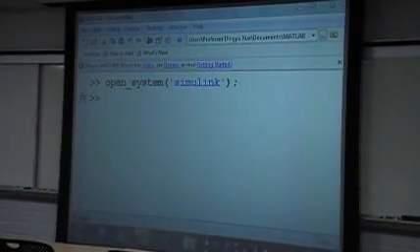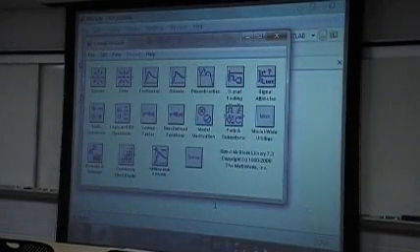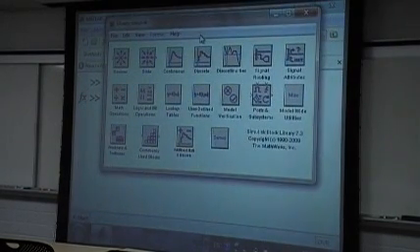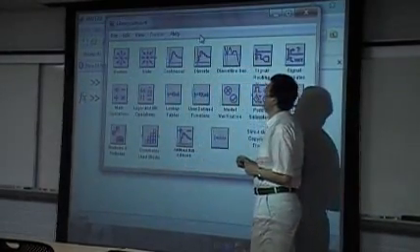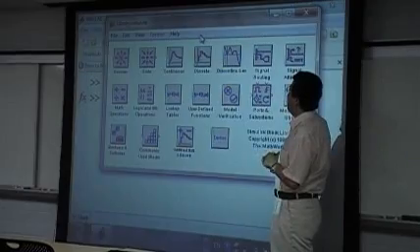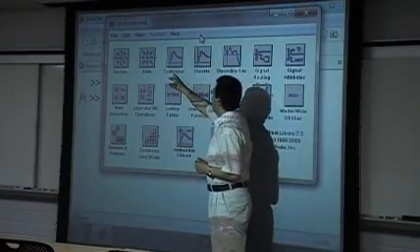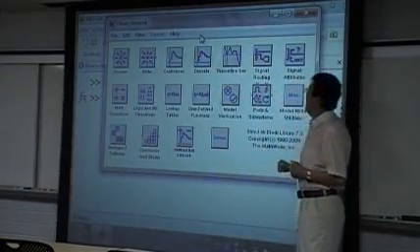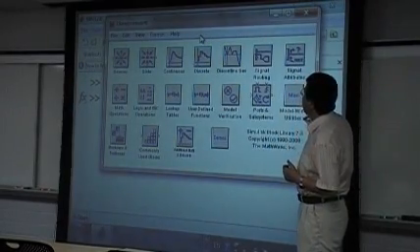If you start Simulink, you will have a library window like this, where you can see that there is a sources group, which is used for input signals. And then this one is used for output signals. You can display messages, graphs and other things with these blocks. And you can model continuous linear systems, discrete linear systems, and those for non-linearities. There are quite a lot of important blocks in this library.